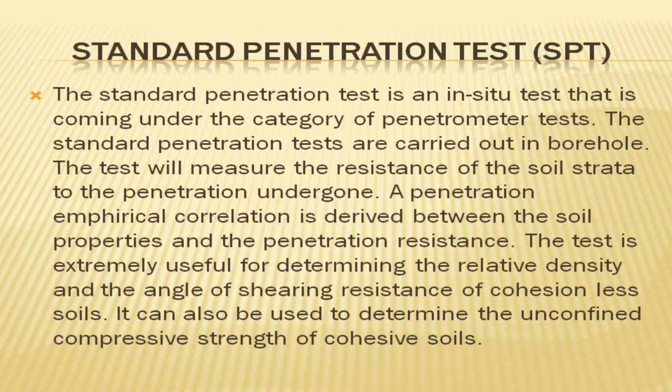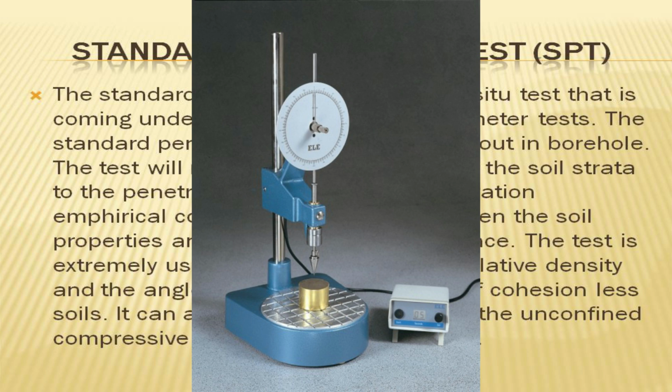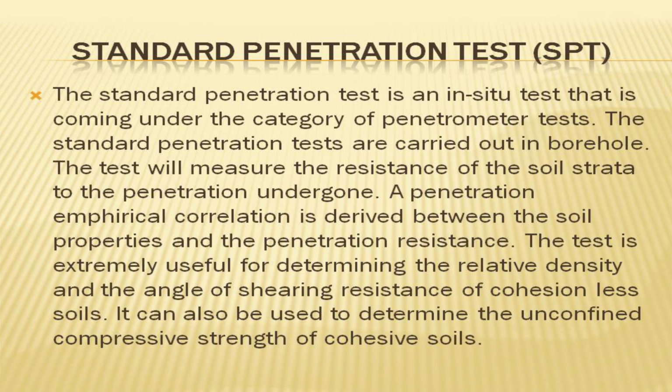Standard penetration test. The standard penetration test is an in situ test that comes under the category of penetrometer tests. The standard penetration tests are carried out in a borehole. The test will measure the resistance of the soil strata to the penetration undergone. A penetration empirical correlation is derived between the soil properties and the penetration resistance.